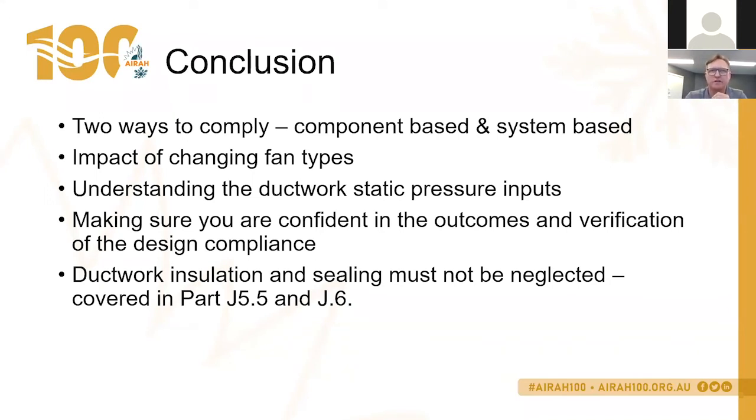That was just a decision that the Building Codes Board made to simplify the efficiency assessment. So the efficiency values are based on clean filter pressure drop allowances. So you should do the same thing in determining your fan efficiency for compliance. Obviously, your selected fan would then need to, from a duty perspective, achieve the dirty filter values. Otherwise, you won't get the airflows in your system and you'll end up with performance issues.